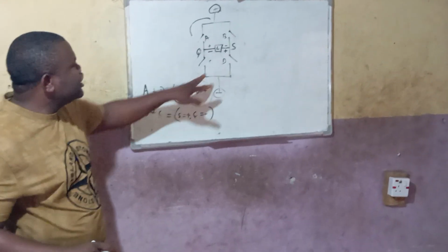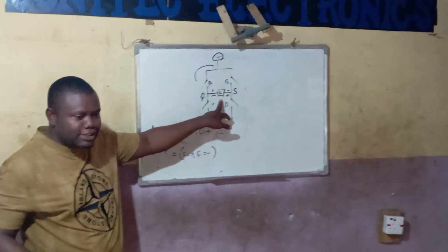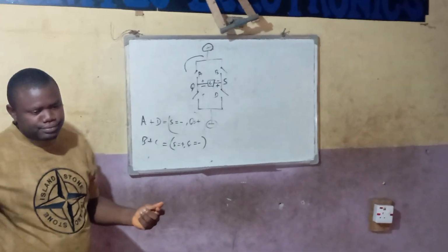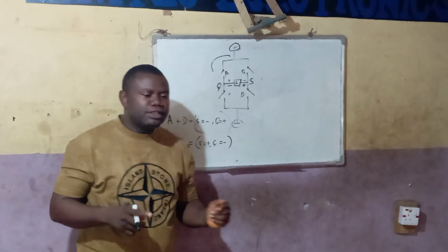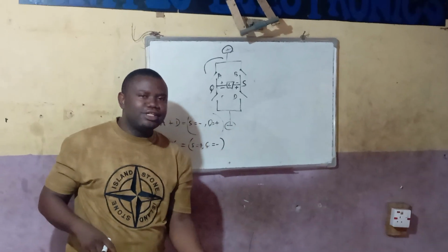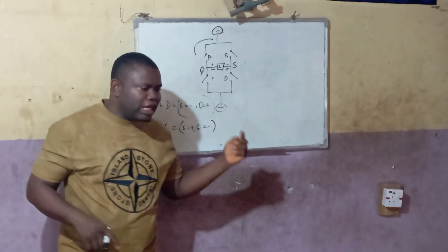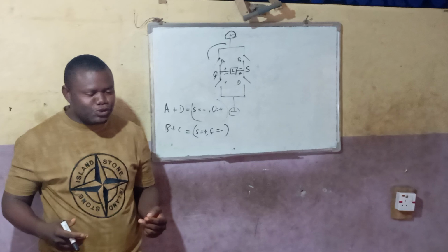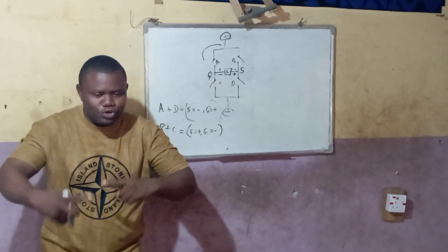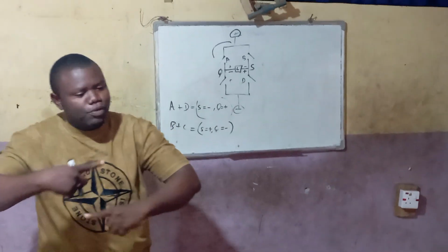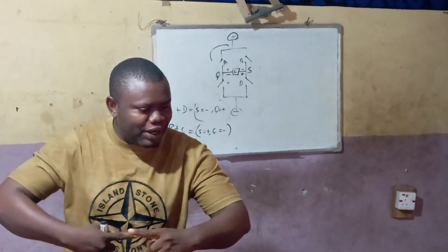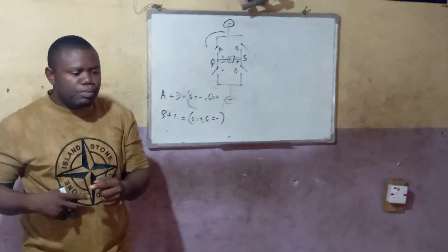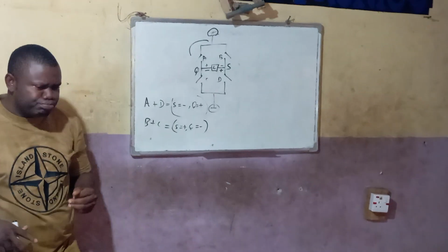If we were powering a DC motor with this, all right, at the first instant, the DC motor may be turning clockwise. At the second instant, the DC motor will be turning anti-clockwise. So let's say you are building a robotic car and you want the vehicle to be going forward. So what do you need to do? You power this one and the DC motor goes forward like this. At some point, you want it to be going backward. You change the polarity, right? It starts coming back.